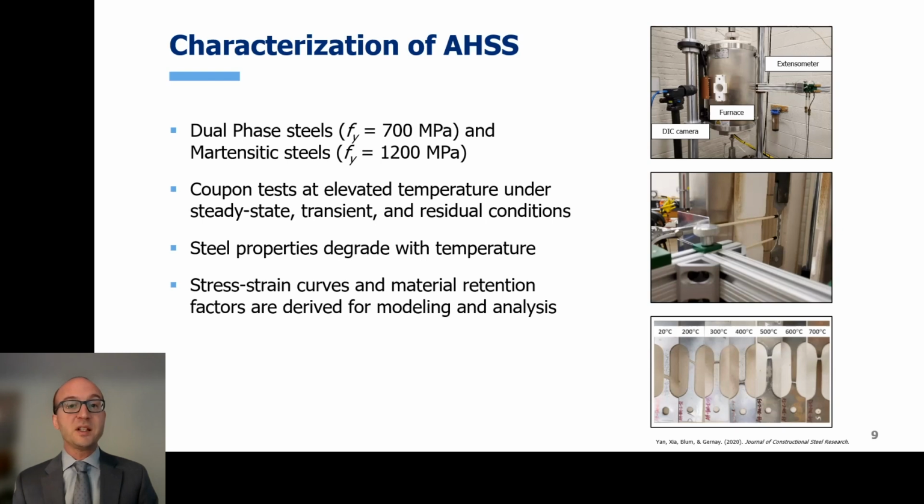There are different testing protocols at elevated temperature. We can first heat and then apply the loads, or on the contrary, first stress the material and then heat it up to failure to find the failure temperature. But what's important is that we conduct this test across all temperatures of interest, and we find temperature-dependent force-displacement or stress-strain response.